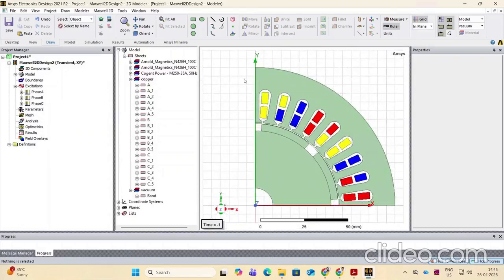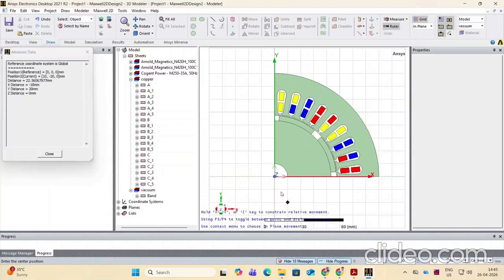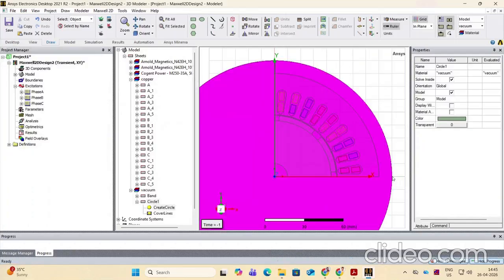So now we have to create the boundary. First thing to create the boundary, we have to again create a similar object as a circular object. We will now create that object in a different way. We will create a circle just to explore what all ways we can draw various things. Snap and click on the center. Expand it, click on any point on x-axis.